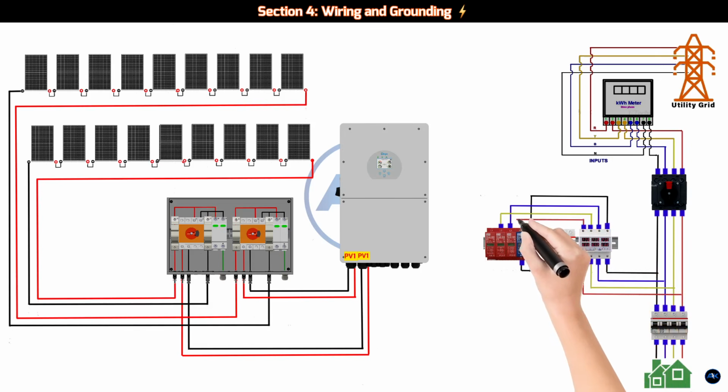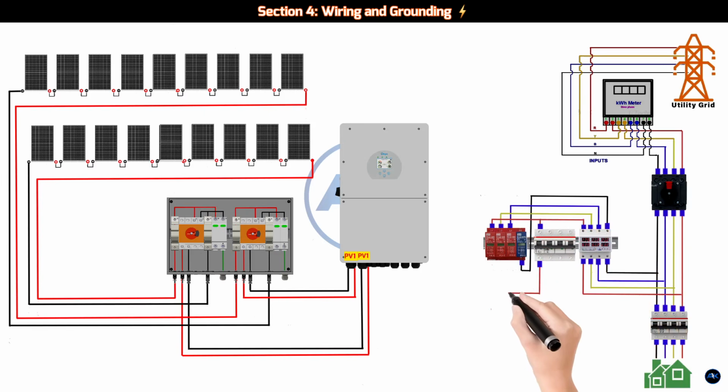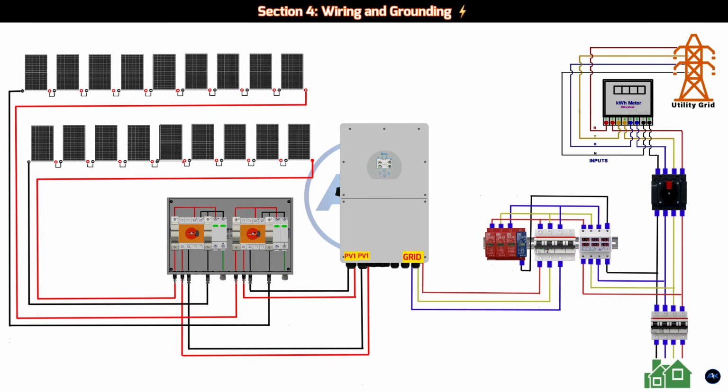2. Under-over voltage relay. Install the under-over voltage protection relay in the ACDB. This relay is a critical safety device that monitors the grid voltage. Connect the grid's 3-phase and neutral lines to the relay's input terminals. The relay's output will then control the main solar breaker.